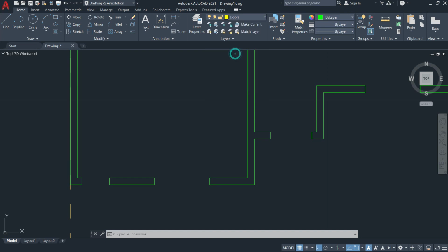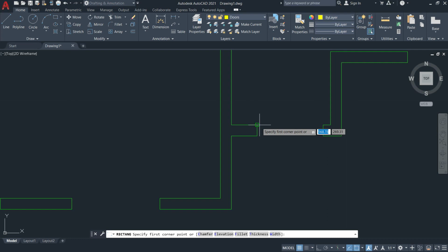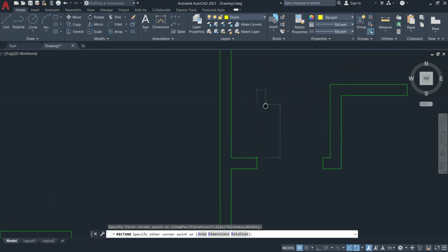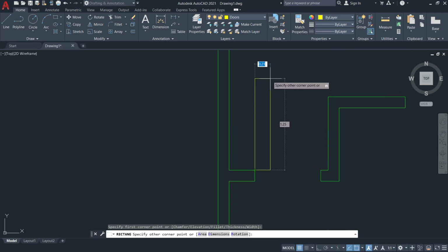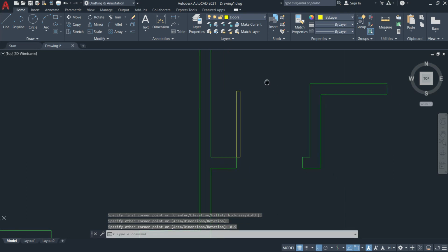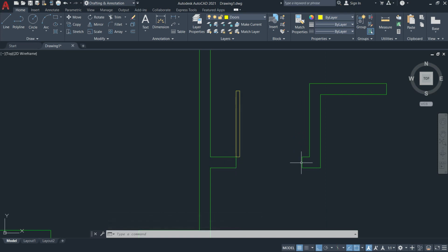Okay, so doors layer, then I'll just draw a rectangle, so provide it here. Okay, so notice that the thickness of the door is 0.05. Just press the tab key, then measurement of this one is 0.9. Enter. Okay, so this will fit to this opening, so that is 0.9 also.